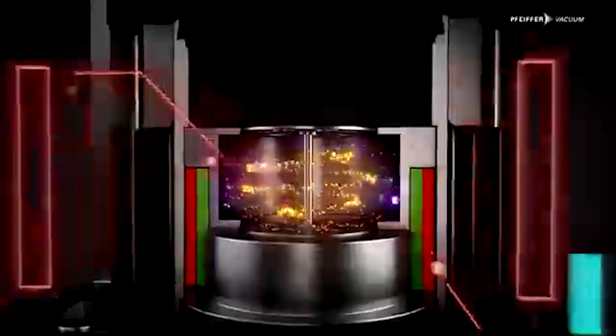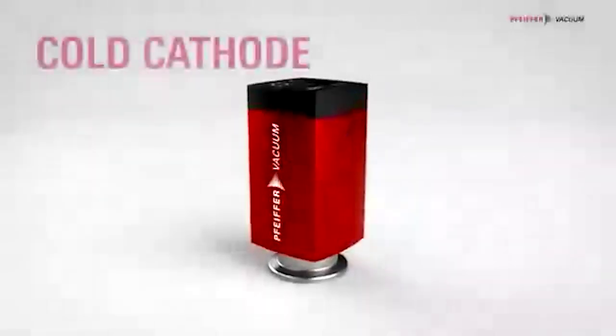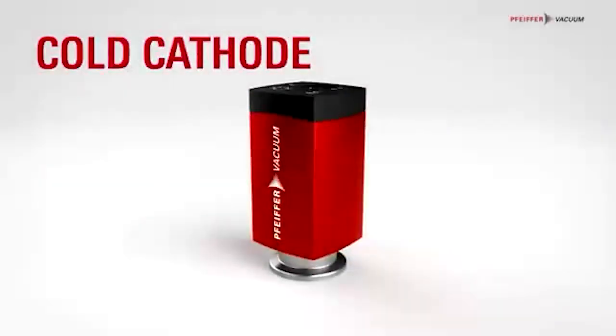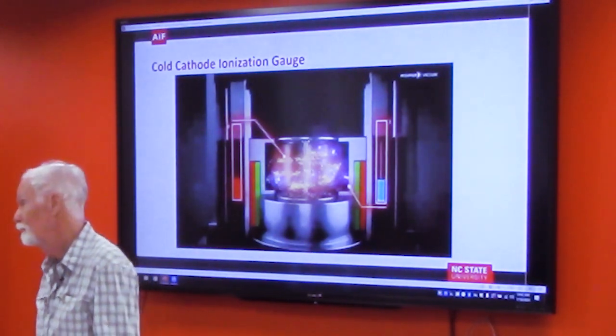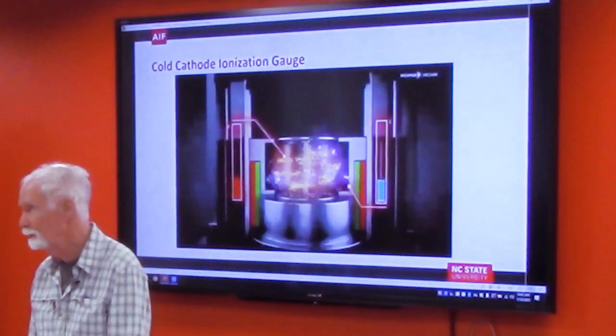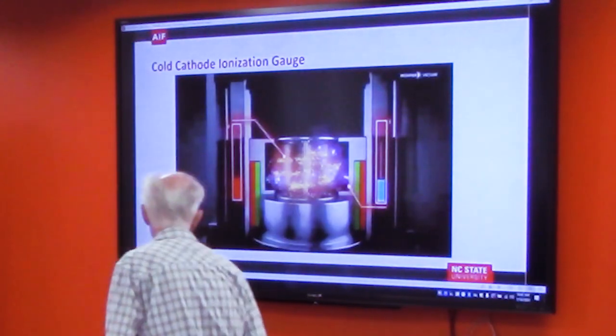So why am I mentioning these prices? Because if you're building a vacuum system, make sure you have enough money, because you don't want to have this little pump pumping this big chamber. I've seen people doing that. And that way, your whole career, you're working with that little pump and that big chamber. You don't want to do that.